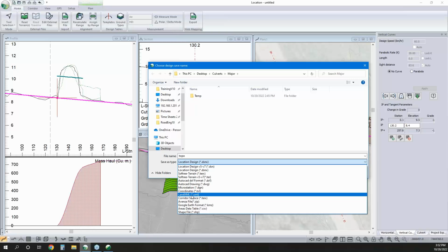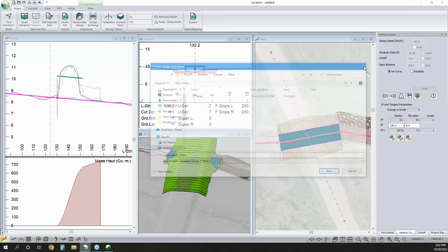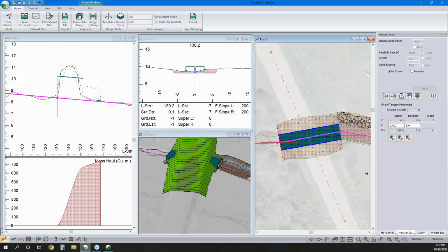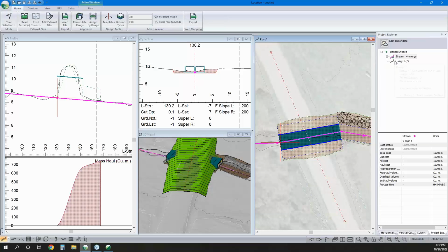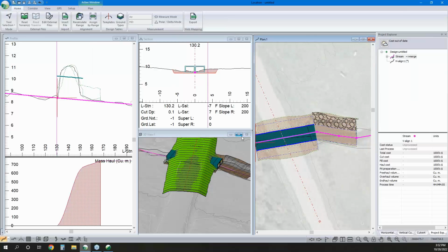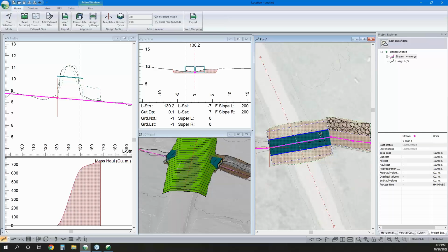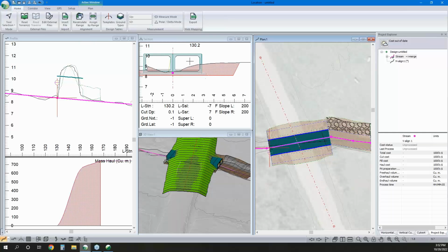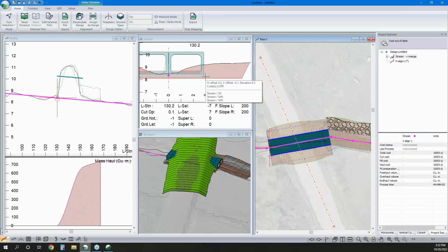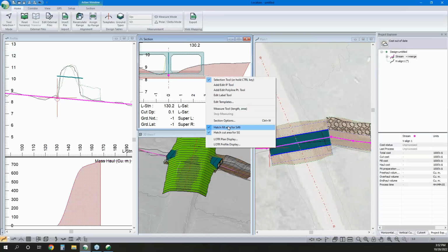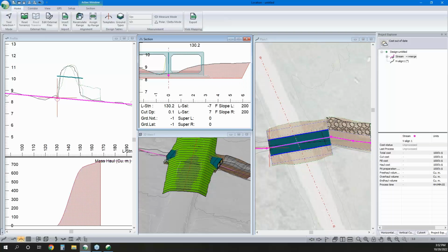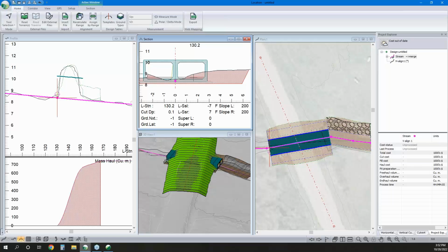All right. So I guess with this, we're going to keep in mind that we've got two different alignments, so they're going to be tracked for two different alignments. So my stream portion here, if I want to see how much subgrade I'm cutting, and I'm not really interested in my concrete quantities, that's going to be paying for the unit. So let's go with surface volume 6 for my leveling course and subgrade. And we've got a little bit of backfill in there to do a simulated stream bed.